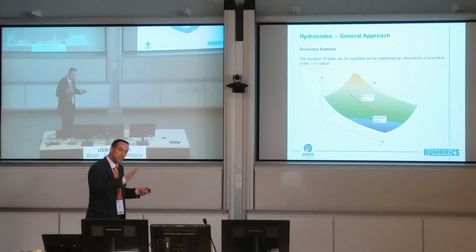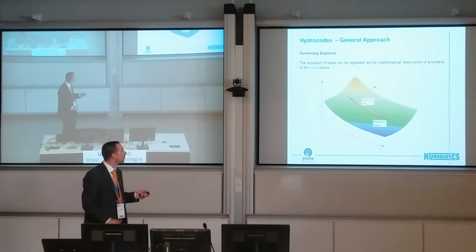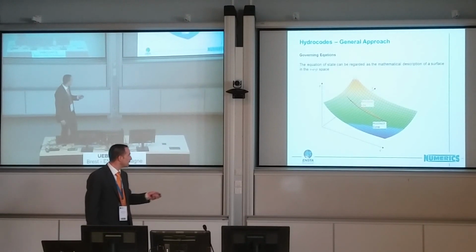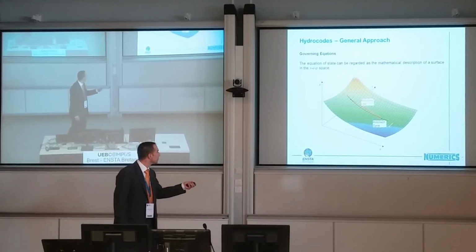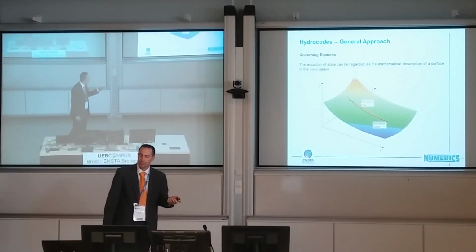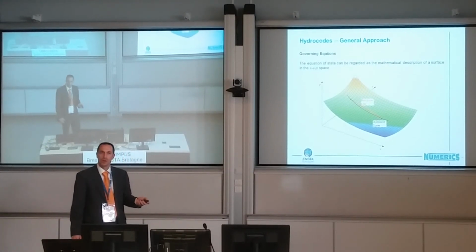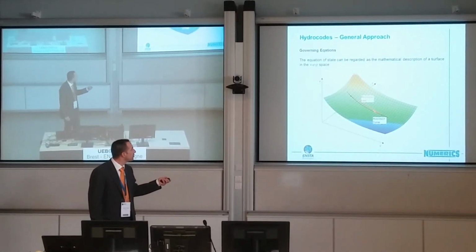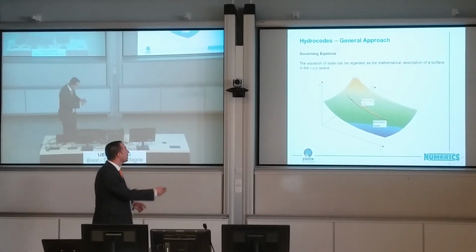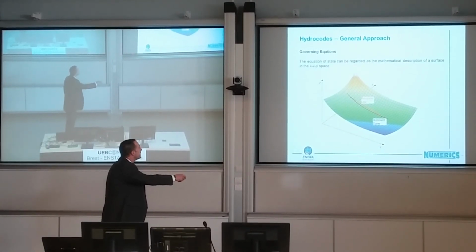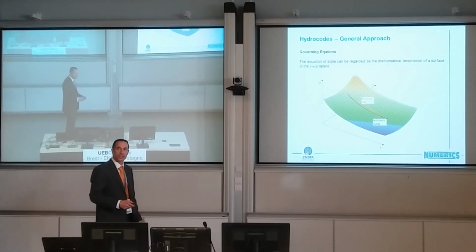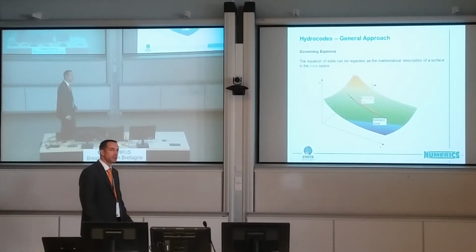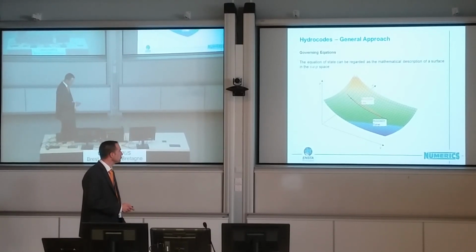We don't go through this isentrope curve, we jump on the Rayleigh line. And this type of curve can be determined in, for example, flyer plate experiments, and then you have a relation here. And regarding the energy direction, there is usually an extrapolation made, which can hardly be measured in the experiments.